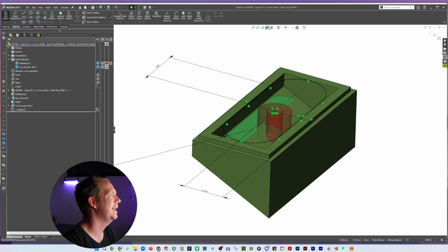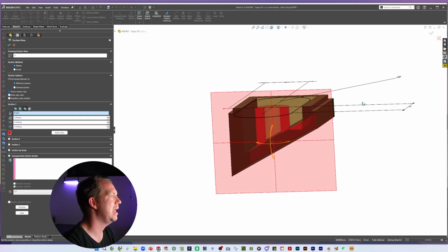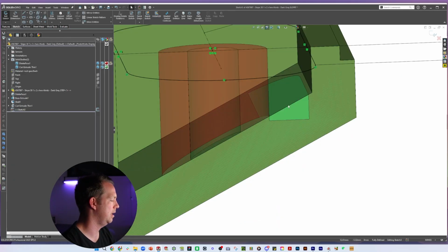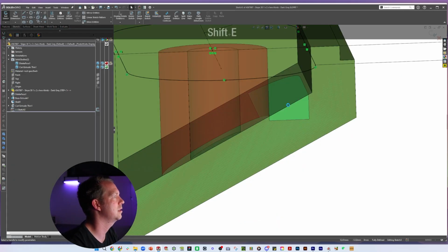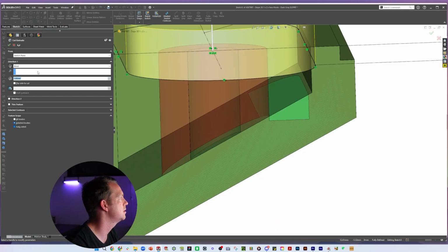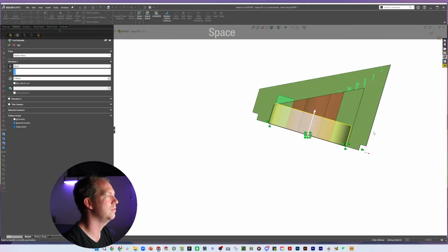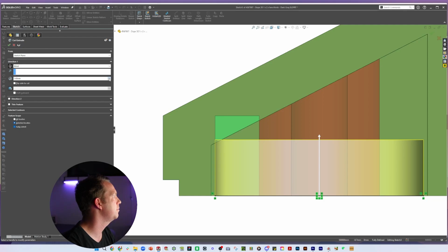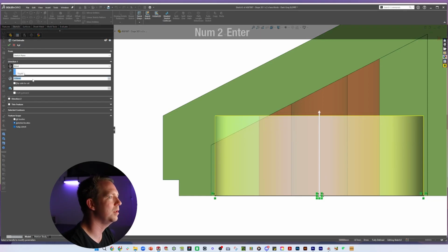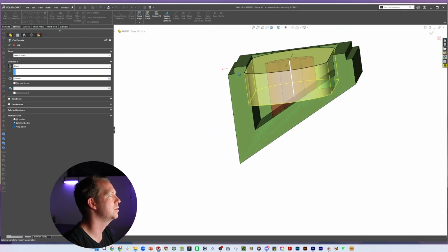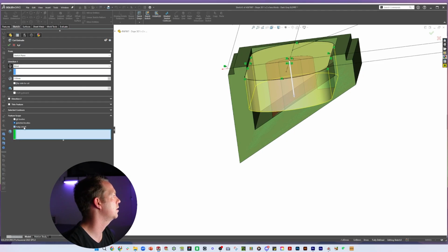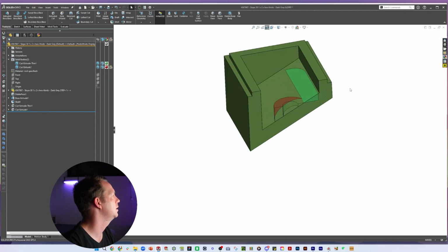All right. Now we're going to do a cut extrude, because we need to go down to that face. And so we're going to do extruded cut, and we're just going to increase this distance until we're getting to that edge. Now, if I go to a section view on the side, I can just bump that up. Looks like it is 2 millimeters, and I want to make sure I'm selecting the right body.